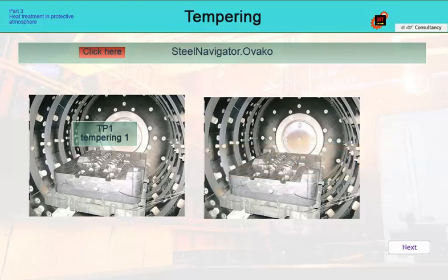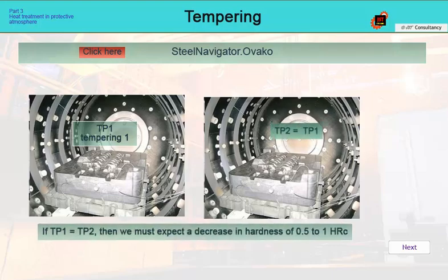However, it is also necessary to take into account that if the hardness does not work out, and we include additional tempering at the same temperature to which the part was tempered in the previous cycle, the hardness will still decrease by half to 1 Rockwell. This is a consequence of the fact that the resulting hardness depends not only on temperature, but also on time, and in this way we have essentially doubled the time at temperature. So again, the rule of caution should apply, and to fine-tune the hardness, we must increase the temperatures very carefully, preferably less than more.